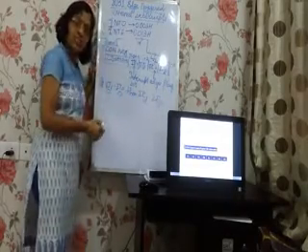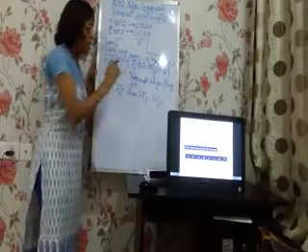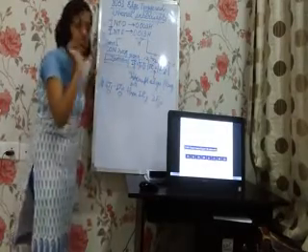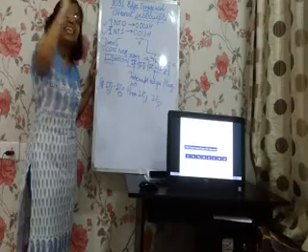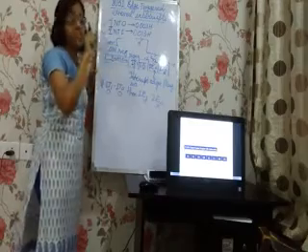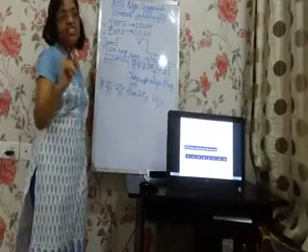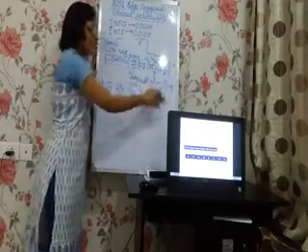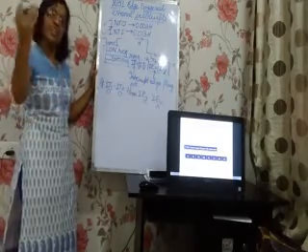What does this mean? When IT1 IT0 are 0-0, the interrupt is a level triggered interrupt. These two bits IE1 and IE0 are specifically for defining edge. So remember, these bits are specifically defined for defining that the interrupts INT1 and INT0 are edge triggered interrupts. That is, the microcontroller has to be interrupted when a falling edge is detected. So if IT1 and IT0 are 0-0, whatever may be the status on IE1 and IE0, the interrupts won't be recognized on edge, because they are already defined as level triggered interrupts.